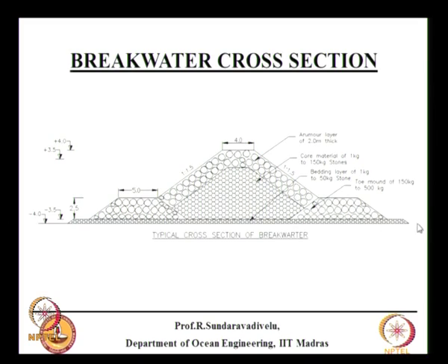So now I will tell you what is there from the bottom. Here we may put a geotextile filter if the seabed consists of clay, but even if it is sand we may put a geotextile filter. Here it is not shown, because with the advancement in technology we have recently started using the geotextile filter.